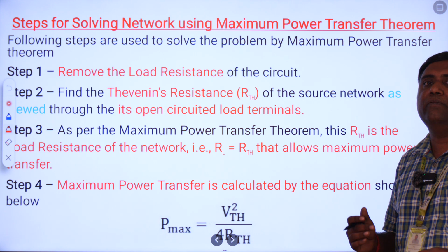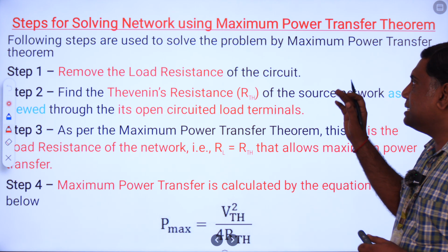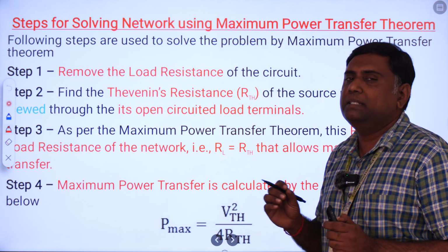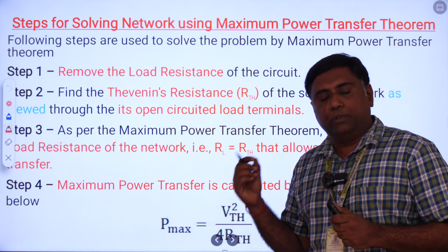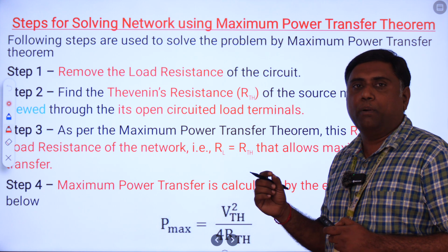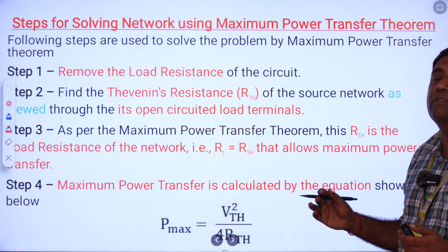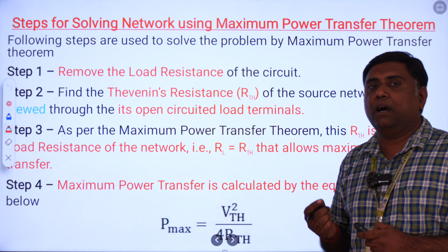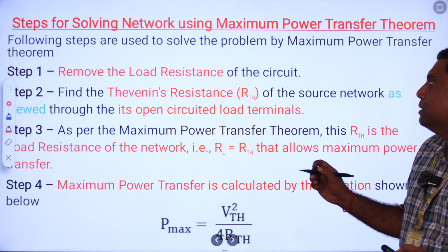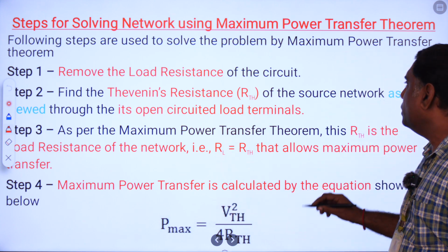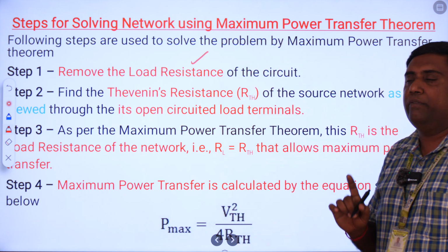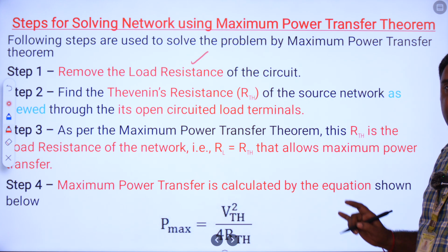Next, we move on to the steps for solving a network using the maximum power transfer theorem. This is very important to keep in mind, because while solving GATE problems we have to follow these steps, which will help us get the value easily. Step one: first, remove the load resistance of the given circuit.